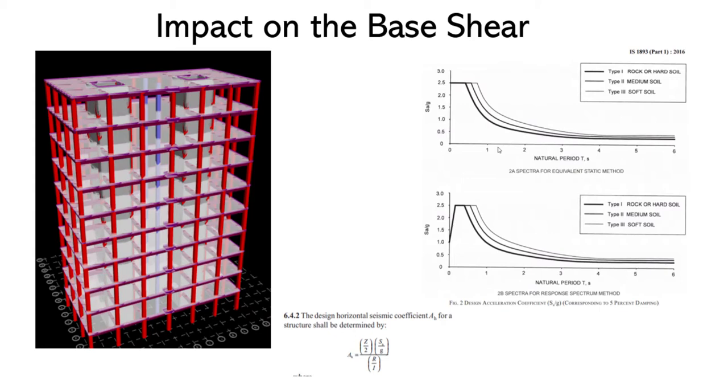So in both cases, you have a difference in the rigidity. That would impact the calculation of the natural period or the natural frequency, and invariably it will affect the calculation of the spectral acceleration and then your base shear. So here you need to judiciously use your engineering discretion to define the floor diaphragm as rigid or semi-rigid.